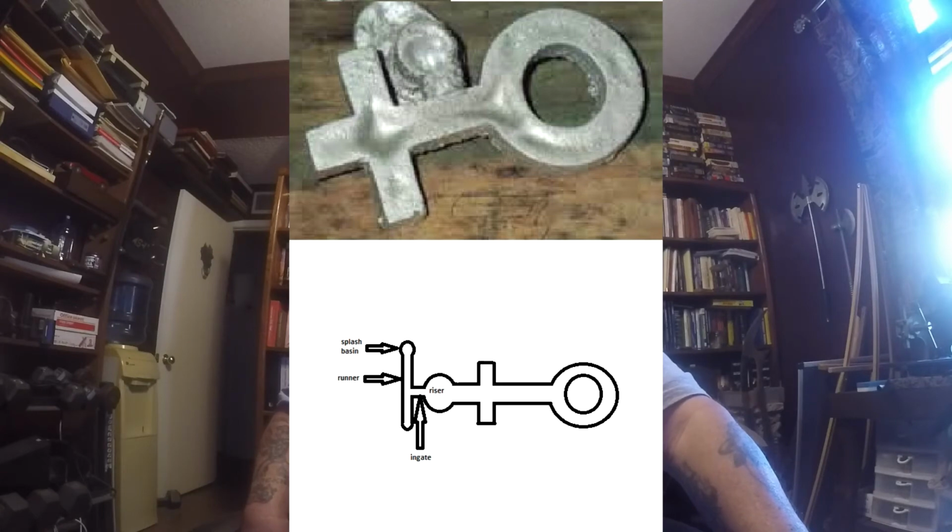All right, so you see on top a bad case scenario where they put a down sprue that was going to be their riser. They made a bunch of dross which dumped directly into their mold cavity, and they poured it so hot that even the base, the bottom portion of the casting, shrank. So you have the good and the bad right there.